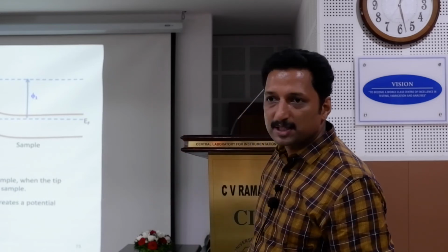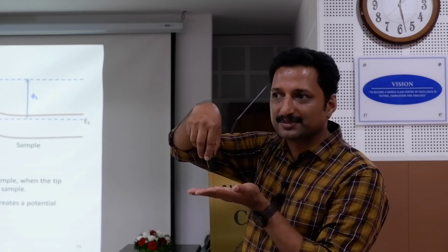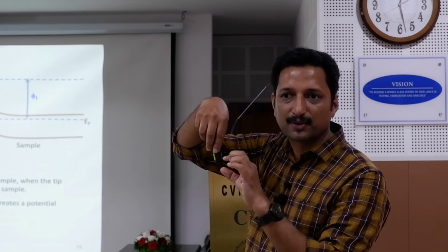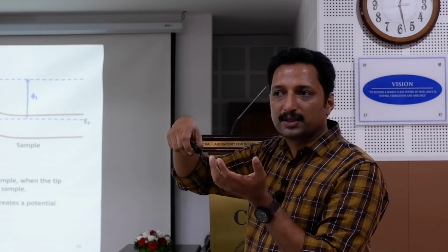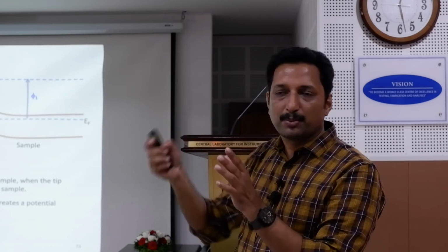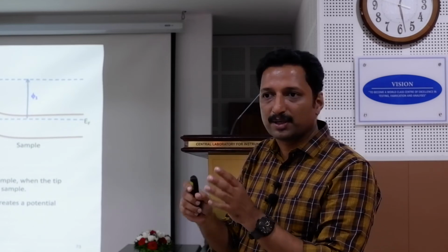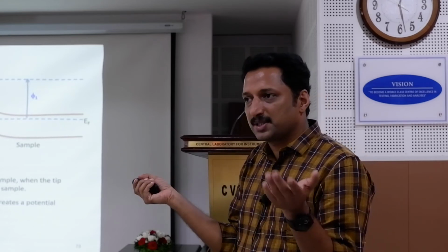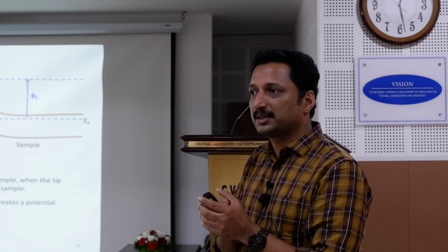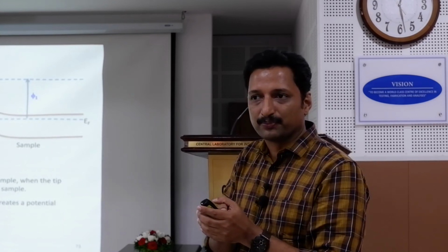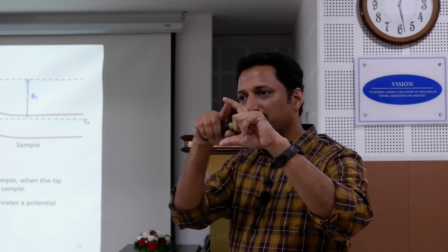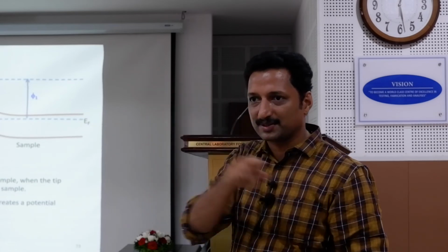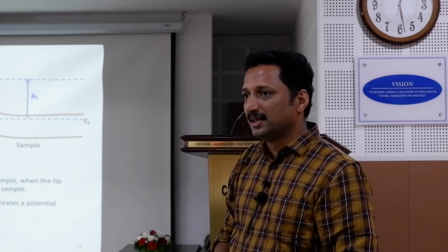This much Fermi level difference means that there is a small voltage occurring there. It's called surface voltage. I don't know whether you remember about Schottky barrier, ohmic contact, all those things. Basically, probably you remember the diodes, PN junction diode. When we put one P and one N together, suddenly we have a structure like this, right? The band diagram we draw like this.